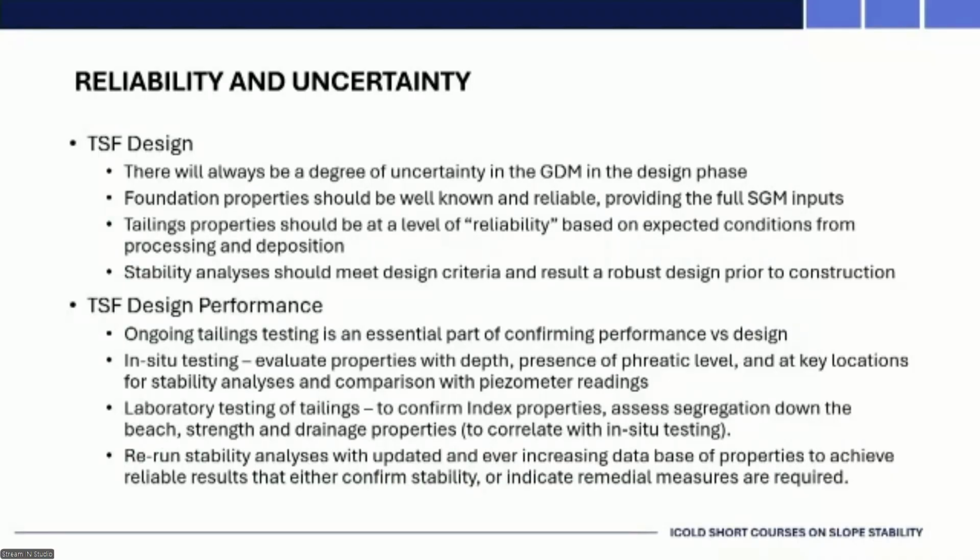So when it comes to the design of a tailings facility, how are we going to address the uncertainty in the geotechnical design model? You may not have good samples of your tailings. You should be able to do good foundation investigation right up front. It's always possible to come back and do more, but it's best to get that done properly up front.